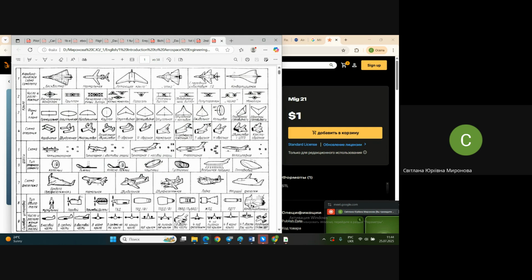Of course, in this case, people make so-called hybrid controls. They may work as flaps during takeoff and landing. You do remember, I hope, that flaps are used only during takeoff and landing, not in normal flight. And ailerons are used for evolutions, for rotations during all the flight.